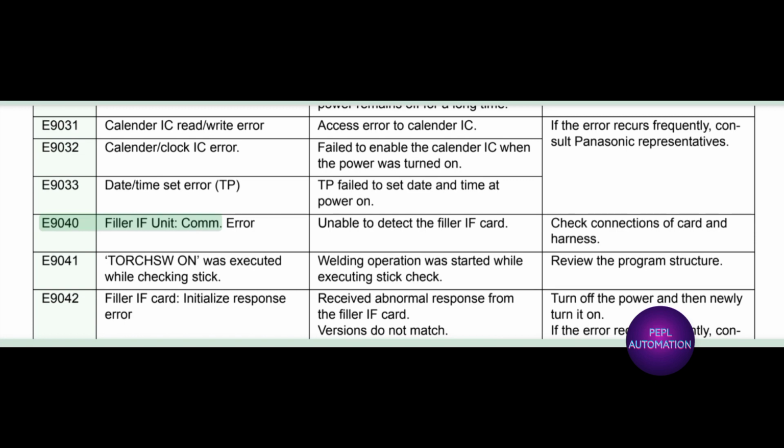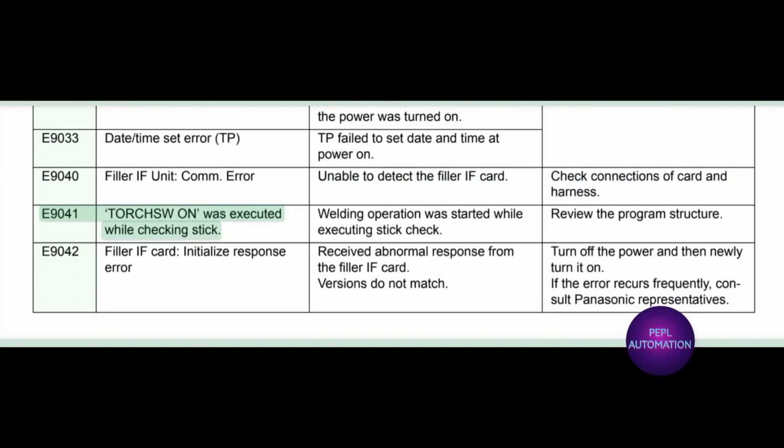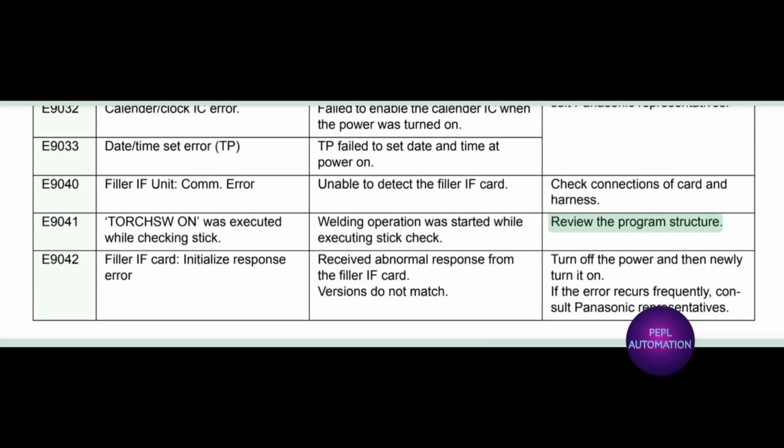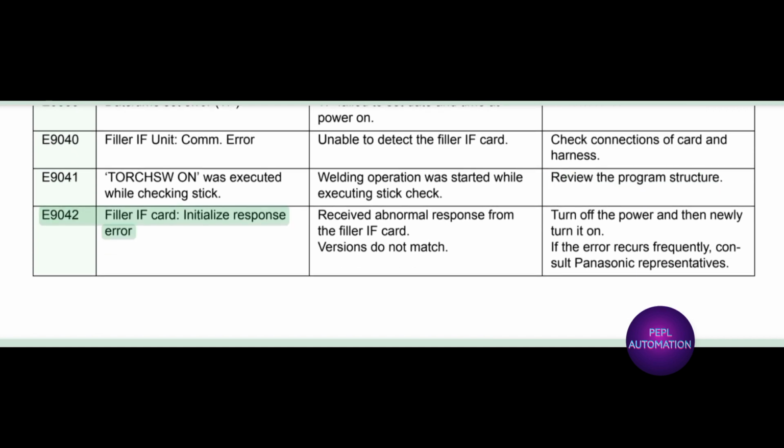E9040, filler IF unit error. Unable to detect the filler IF card. Check connections of card and harness. E9041, torch on was executed while checking stick. Welding operation was started while executing stick check. Review the program structure.